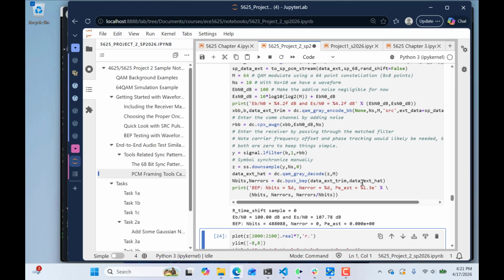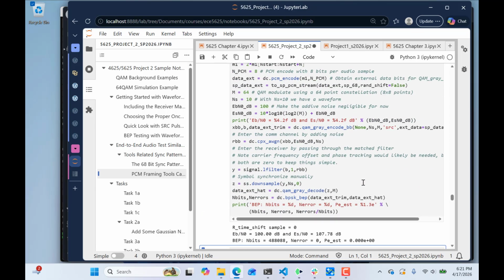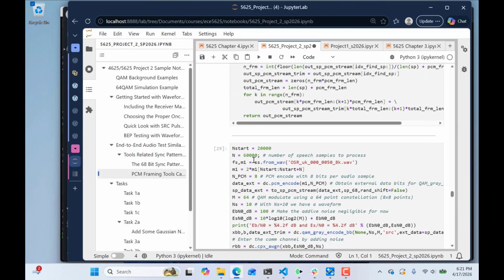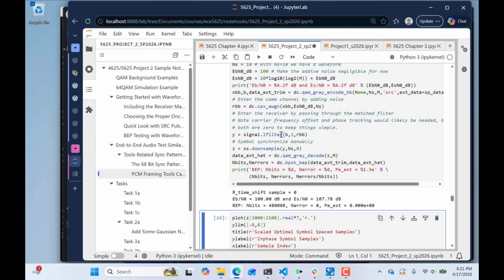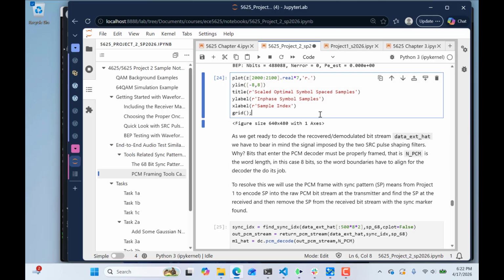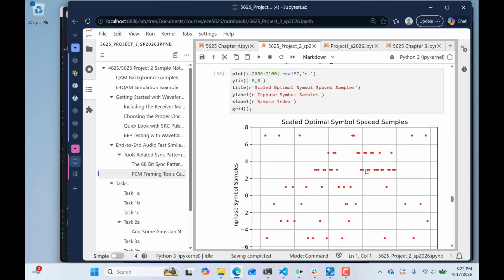And then I come along down here and I implement the receiver on this. I do that right in line here, but I have it a different setup, I think, for example, for sampling. So I come down here and I'm reading my code again. I encode, add noise, match filter, manually synchronize. This takes the place of a phase lock loop. Gray decode, do bit errors. Okay, so I have that done. There's no noise in these, so they're not doing much of anything. They're just like straight lines again.